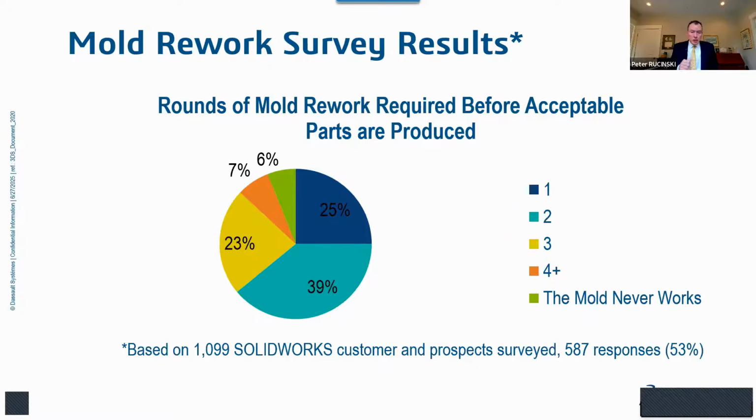And one of the biggest topics of discussion in the design review is simply the gate location. Where should the part be injected with plastic material, with the melted plastic? So they kind of scratch their heads. They look at the proposed design. Everyone says, looks good. So they move forward with the mold manufacturer. They get the mold made. They put the mold in an injection molding machine. They load it up with plastic granules.